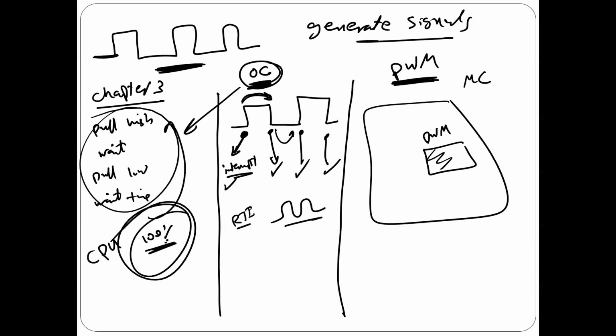Okay, very interesting. So all you have to do, guys, here, the microprocessor has to initialize, or has to do configuration to the pulse width modulation. So for example, in the configuration, I'm going to tell the pulse width modulation, I want to generate a 1K hertz signal. Is that okay? For example, so you need to do some initialization.